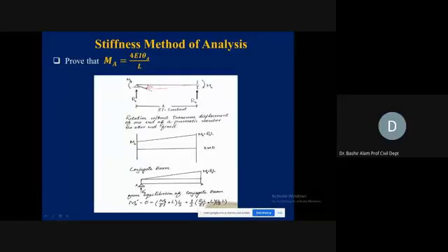So what will be the moment here? It will be MA plus RA times L if we take moment of forces at joint B. So it will be MA plus RA times L, which is shown here at the right. So this is becoming the bending moment diagram. In between the member, we don't have any load, so it is going to change by a straight line. For this given condition, MA plus RA times L is actually MB. This is the bending moment diagram.